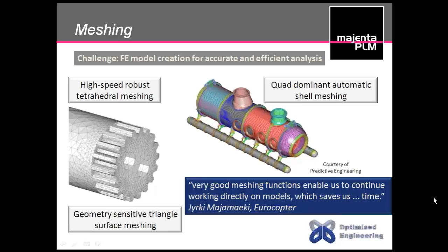So there's a number of different types of meshing that can be carried out, from the automatic tetrahedral meshing, which is great if you're dealing with 3D solid models that have been developed in CAD. And because the auto mesher can deal with a wide range of different geometry types, it will produce an efficient, robust mesh with kind of minimal interference, as it were.